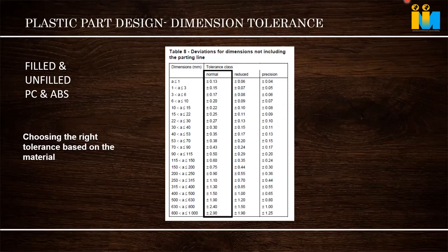Unnecessarily, to make our drawing easily, don't give a tight tolerance, because it will impact our cost of the mold, and deviation can come anytime. Product rejection will be high, and our molding setting is also very, very critical. We will not get any window to operate. So all these are connected. It is a huge connection. Throughout the lifetime, people have to struggle with that tolerance. So relax, give generous tolerance wherever possible.